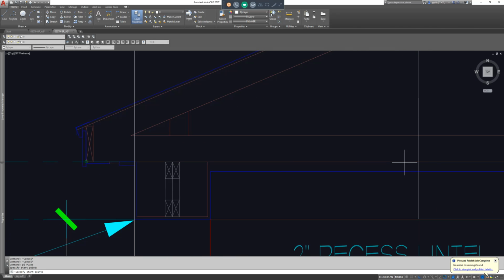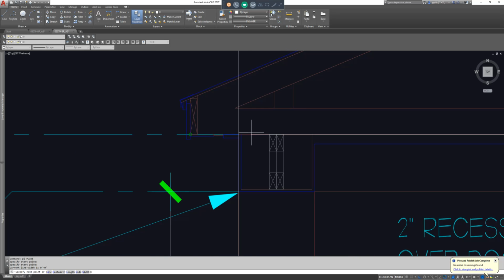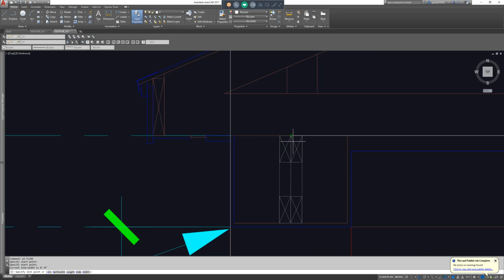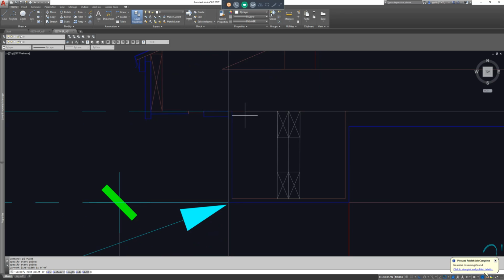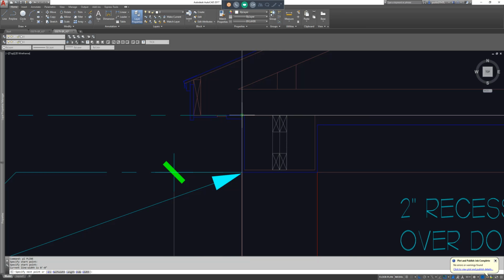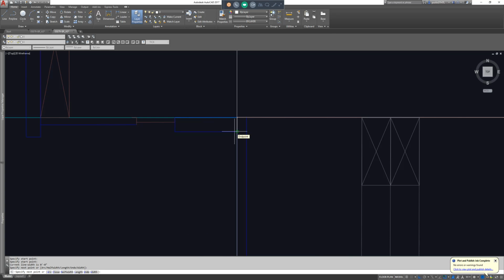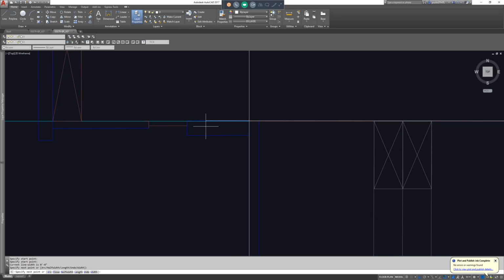So now I'm just going to make a polyline, and I go from the underside of the truss line, and I'll go over typically the block, but here it's just a girder truss, but I'm going to go to the face, and then I'll go down. This is a whole vent system and all that kind of stuff, and you can put as much detail as you want into it, but I'm only just going to go perpendicular to what would be the soffit material.